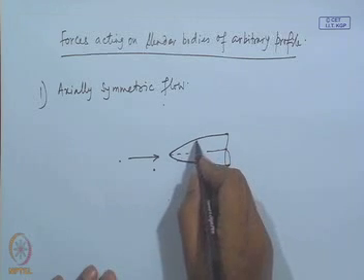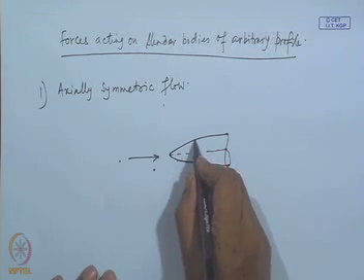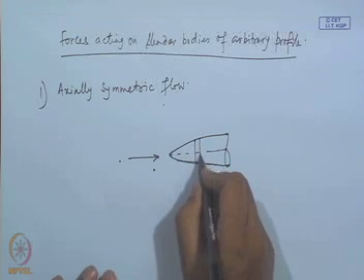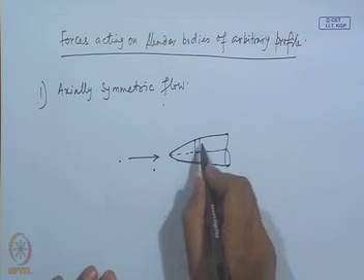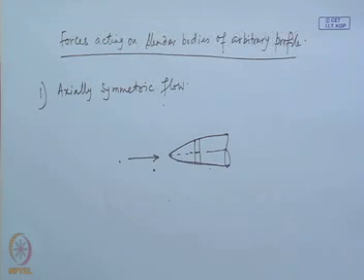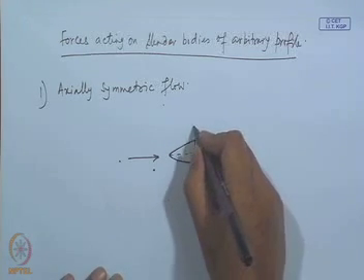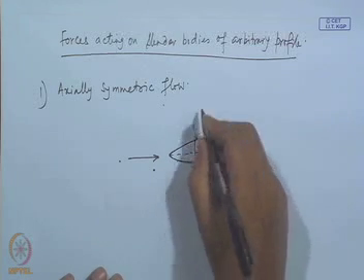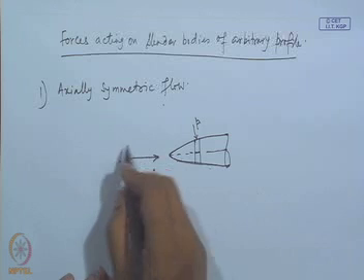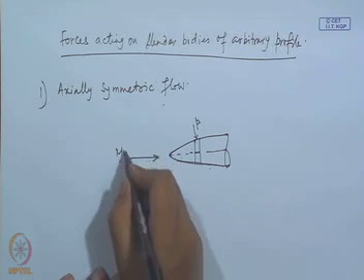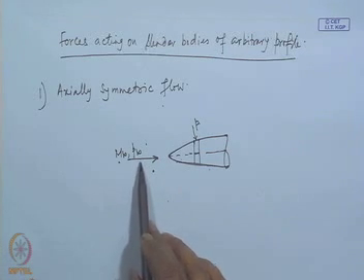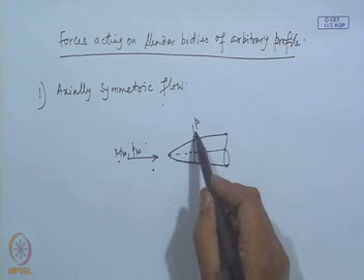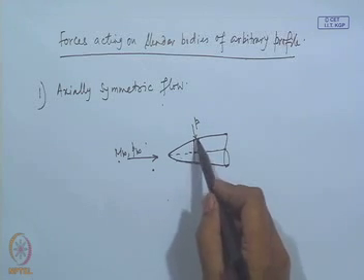Now, if we consider any small axial section over which the radius, or we can say the cross sectional area, is increasing slightly, then we can see the pressure that is acting on this strip, where M infinity is the free stream Mach number, the free stream pressure is p infinity, and on this section the pressure acting is p.